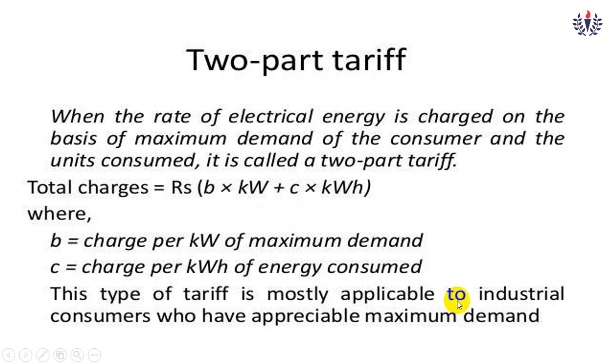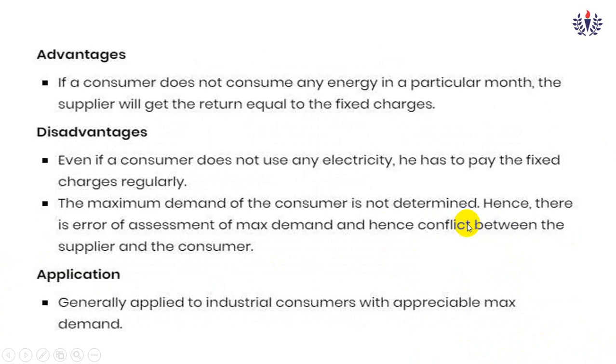Here this tariff is mostly applicable to industrial consumers, as I told already, who have the maximum demand. Maximum demand is, for example, if there are 24 hours, they may consume the maximum value of the load, or maximum amount of kilowatt, at a particular time. For that maximum demand they will charge, and they will keep it as a reference. Based on that they will charge. While doing the problem we may get a clear idea.